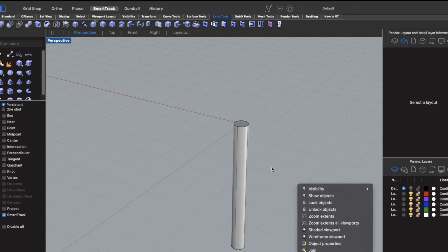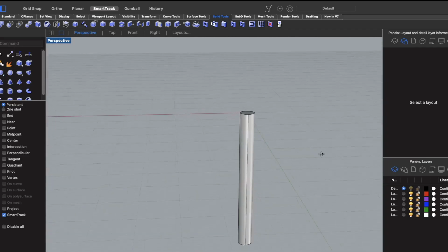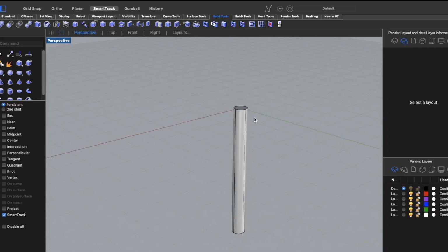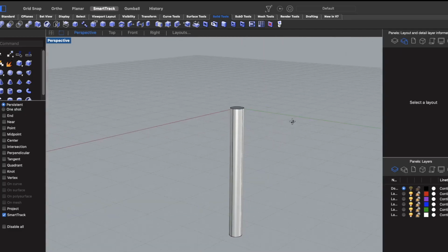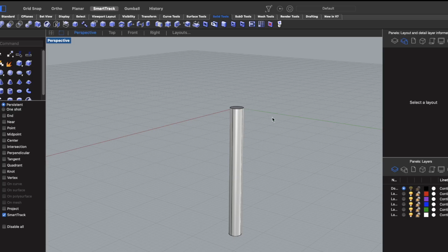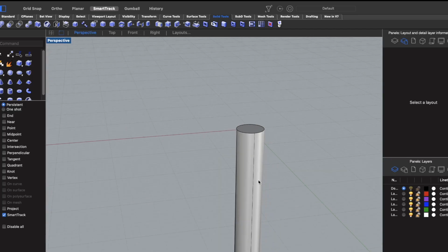That should be fine. And so for HAMS, you only want to model the submerged part of the platform. So even if there was a significant portion above the waterline, we don't model that when we use HAMS, only the submerged part. And it's going to assume that z equals 0 is the waterline. So it's going to assume that this face right here is going to be our water plane mesh.